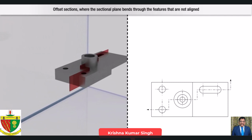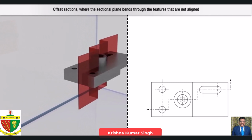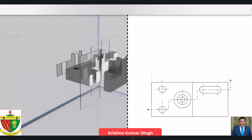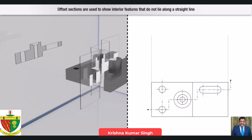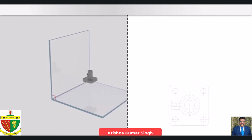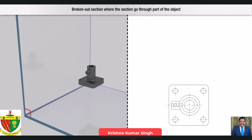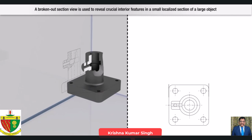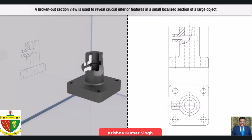Offset sections, where the sectional plane bends through the features that are not aligned. Offset sections are used to show interior features that do not lie along a straight line. Broken out section, where the section goes through part of the object. A broken out section view is used to reveal crucial interior features in a small localized section of a large object.